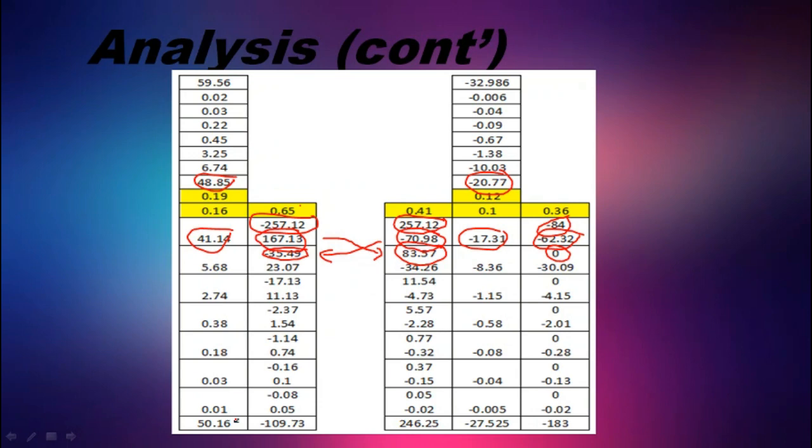For instance, we will get these values for the lower column of joint A, this value for AB, and this value for the upper column. The right table will be done the same. So we'll get these values. These values represent the moments for the members at the joint.